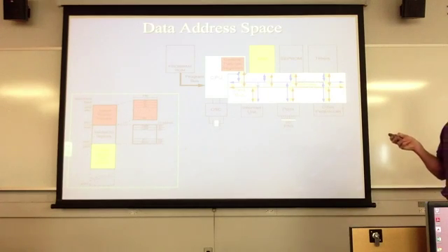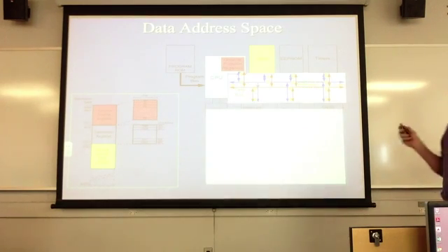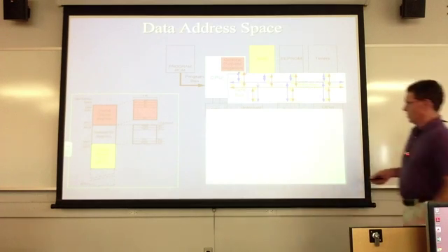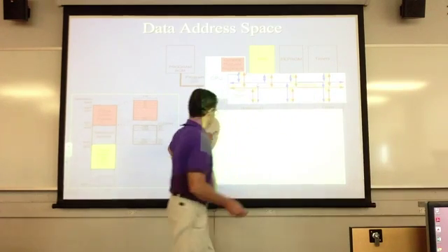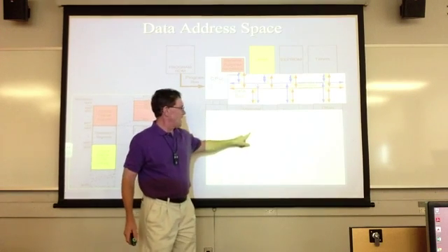In this data address space, we have RAM. We're now going to look at some of these ports over here. We're going to look at some of the I/O pins. I don't know why this came up really light, but I'll have to try to fix this. You have what's called an IN command. Sorry, it's really light, but IN, Rd, and an I/O address.